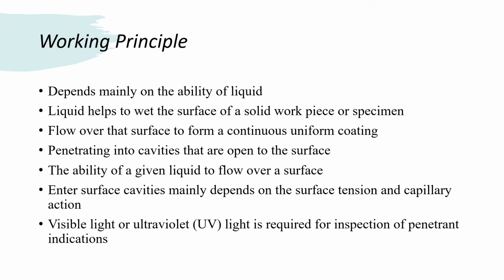Viscosity is another factor, although it has a negligible effect on the penetrating ability of the liquid. It affects the flowing ability of the penetrant. Very viscous liquids are unsuitable as penetrants because they do not flow rapidly enough over the surface of a workpiece. Consequently, they require excessively long periods of time to penetrate into fine flaws.